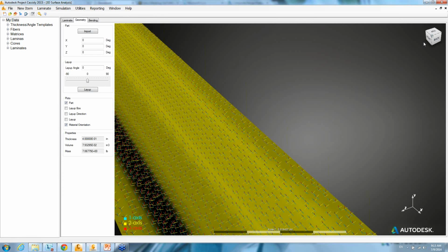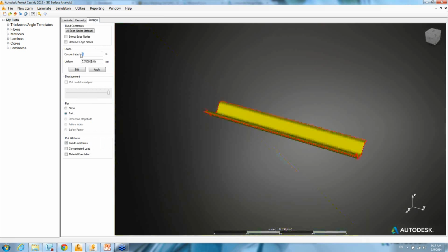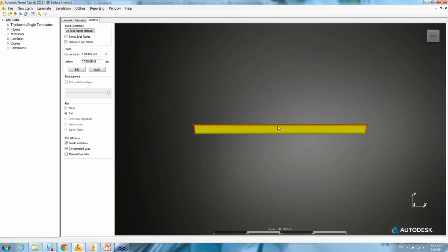And then I was also concerned about hauling the trailer in the mountains or down a rocky road where it may encounter some impact. So I wanted to simulate a point load where a rock may encounter this. We can edit the load. Here you can see that it's projecting on this surface. Deselect that. I can move this more to the bottom, simulate the lowest point where it may impact something that I'm pulling it over.